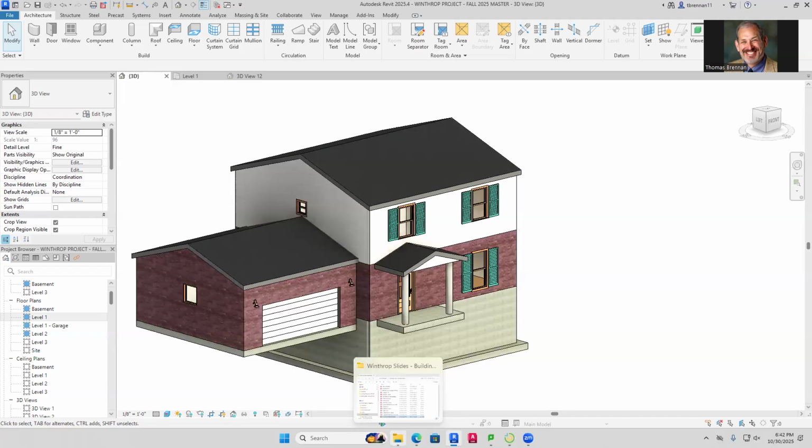The 3 feet dimension at the top left. Well, that explains it. I have an arrow there, a leader, wall foundation, bearing footing, 36 by 12. So that's essentially 3 feet wide by 12 inches. And that's what that is. So that's what we're looking at right there. Yeah, and then the rest is just the floor. Good. Okay.